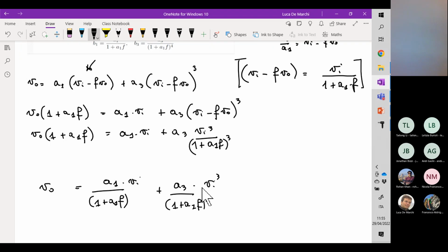So the bottom line is that in the initial situation, corresponding once again to the black solid curve, the phase margin should be computed here, because this is the angular frequency which corresponds to a unitary loop gain.